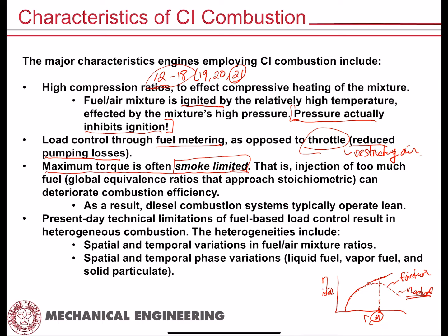So you end up increasing the fuel pressure substantially, right? Sometimes at least an order of magnitude, in some cases even 2 orders of magnitude higher than the pressure of the compressed air that it's being injected into, right? And so that then allows you to do what we call penetrate, right? The fuel penetrates the cylinder. It cuts into that compressed air environment. And so you basically have this liquid stream flowing into the compressed air, okay? So now, again, visualize with me. You have this liquid stream of fuel penetrating into your compressed air environment.